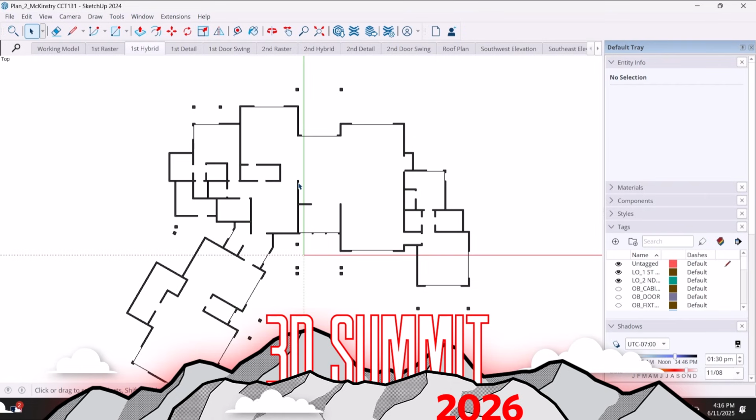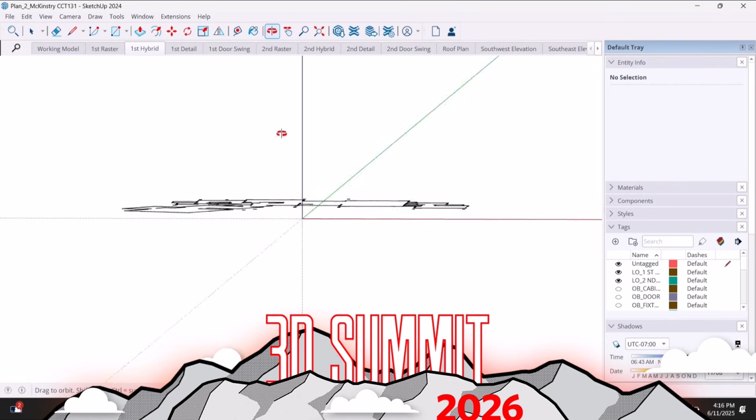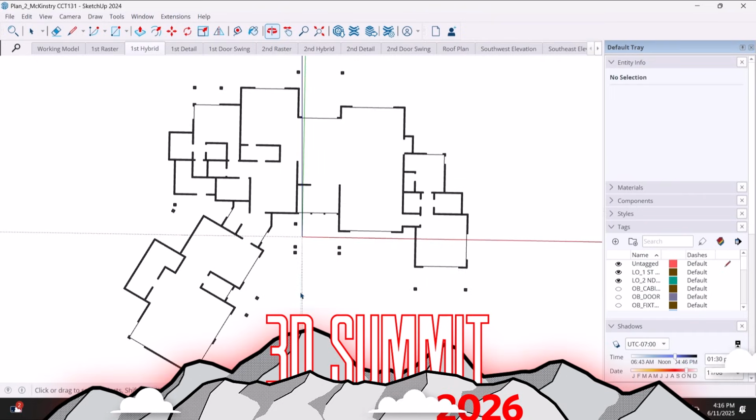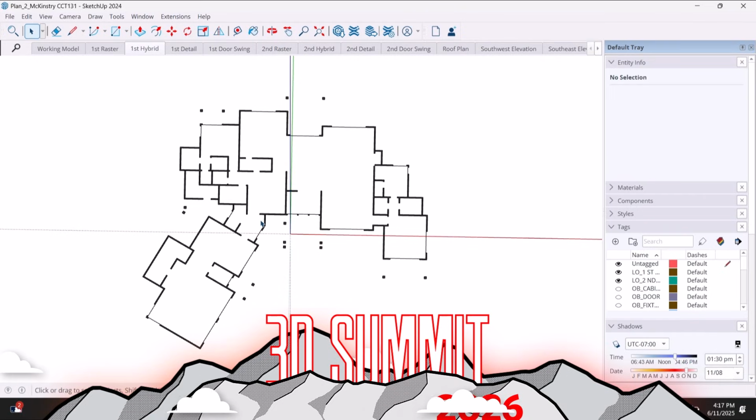There is nothing above or below it. If you look through here, it's just that section cut. And it's dynamic, which is nice. Anytime I move that section cut or change anything with the plan, all the line work will change with it. So it's very simple. And so I'll have that specifically for the walls. And this really identifies the structure in a very bold line in layout.